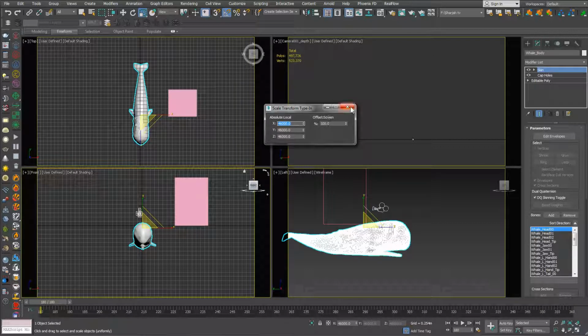Actually, when we import everything from Maya to here, we need to take into consideration to set up Max in centimeters, importing everything from a system which considers centimeters as its units into another program which deals with the same units, or to change Maya into meters, make sure that everything is right there and import it here in Max with a meter setup for the units.